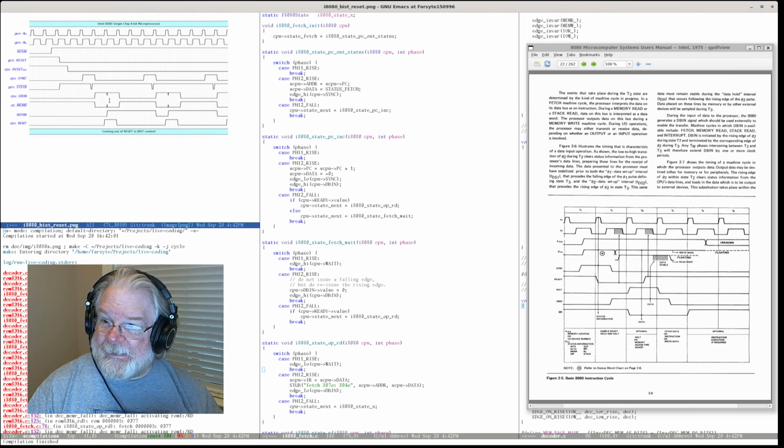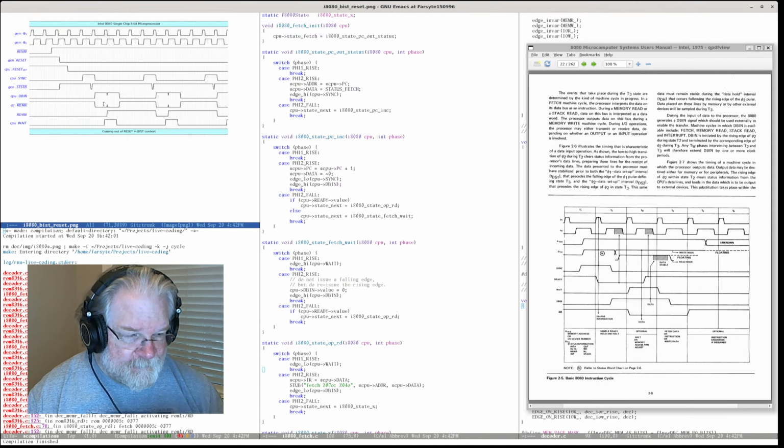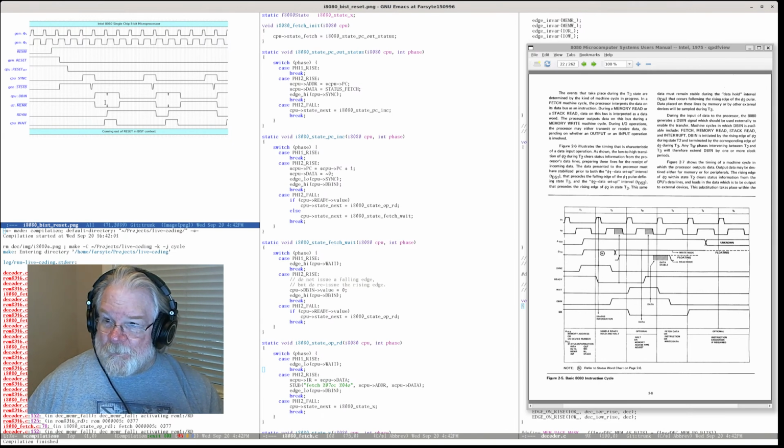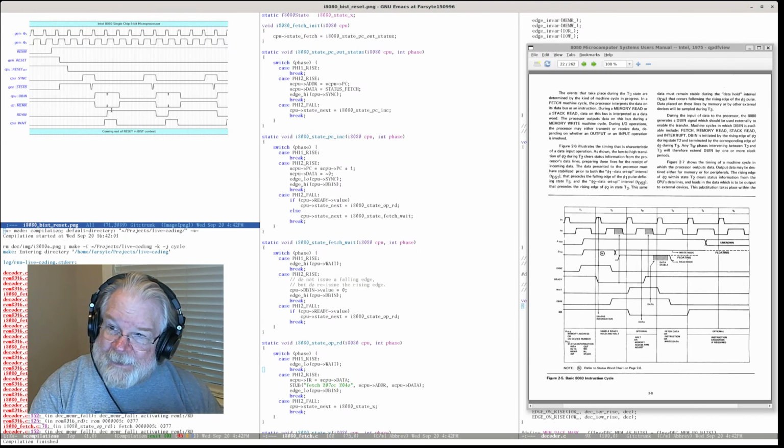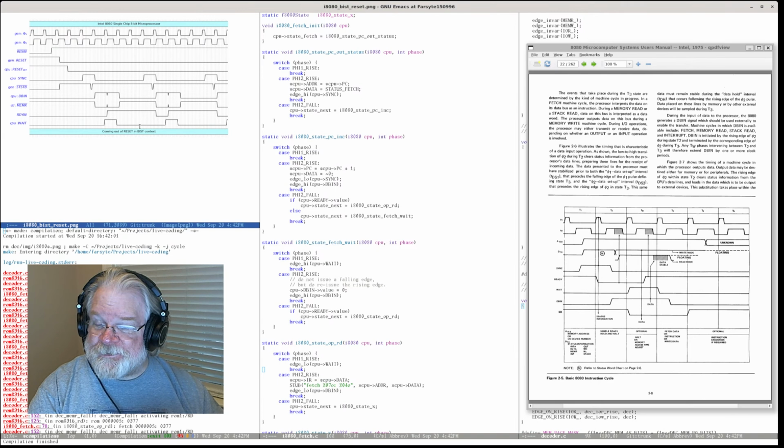We have little spikes on memr and dbin, telling us, yeah, we are reasserting that and we're providing an edge for the downstream stuff. So for simulation purposes, I know that we're getting an edge there. The actual signals as drawn for the CPU will have just a horizontal line across there. That's fine. It doesn't go all the way down, so we know we're not actually outputting a 0 at any point.